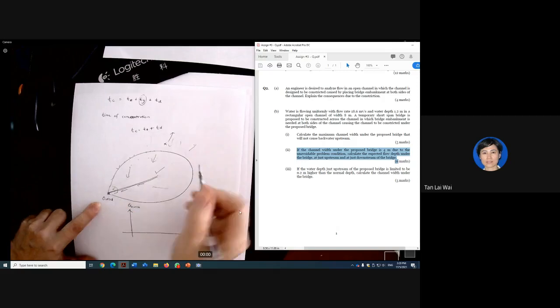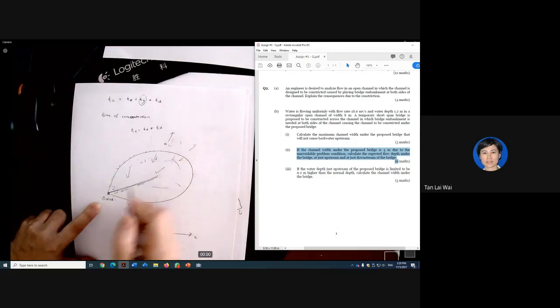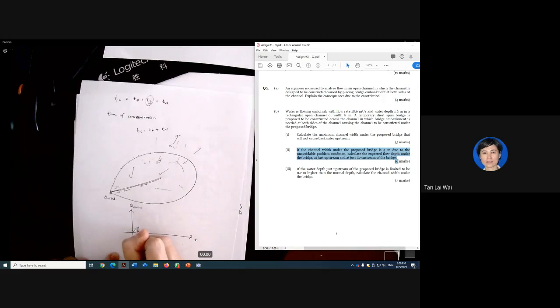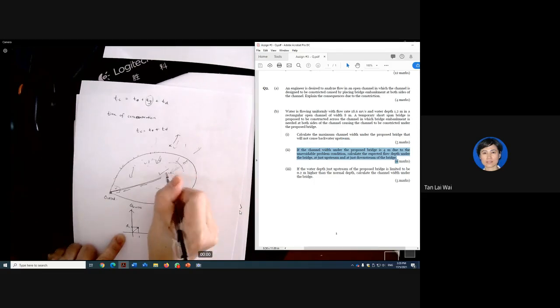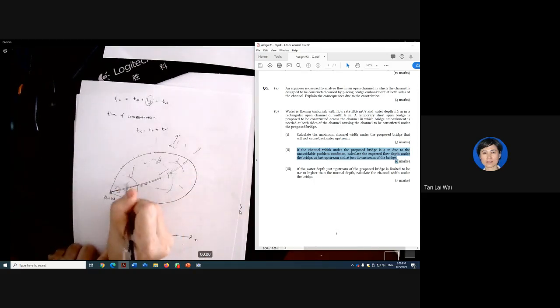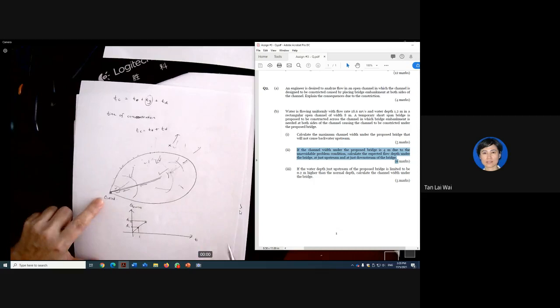In the first minute, the runoff will only reach this point here. It hasn't reached this point, so I can plot my Q only here at the first minute. Let's say Q1. Then second minute. If the rain never stops, if it rains continuously, then you are going to have more runoff reaching and more runoff coming out already. So higher runoff. Then after that, when it reached TC,